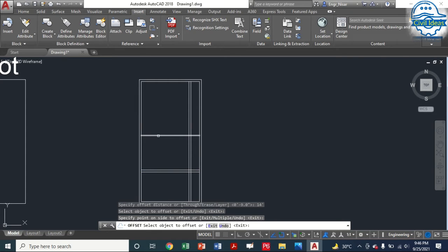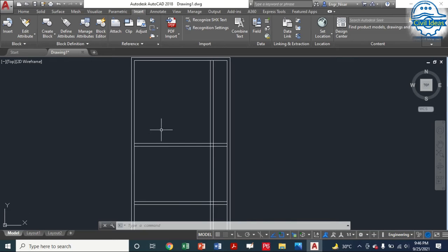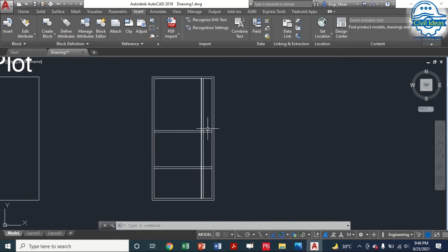This is the ground floor, and offset 9 inches. You have to provide a 9 inches wall here. If there is a washroom, then you may provide 4.5 inches. Okay, so this is some of the rooms, and here you can draw. You can see that DI enter, and first point and second point you can see here the 21 feet. So we have to leave the garage area here.